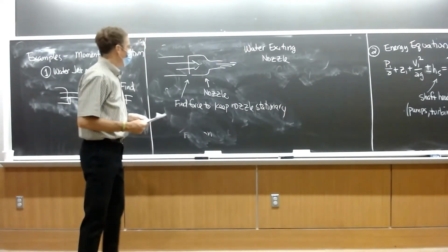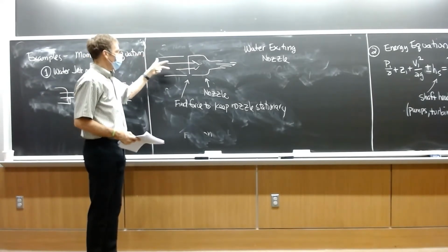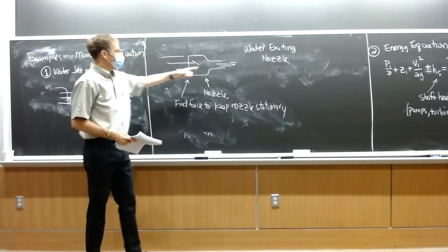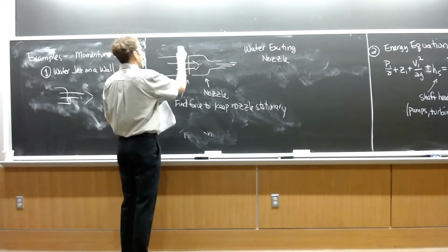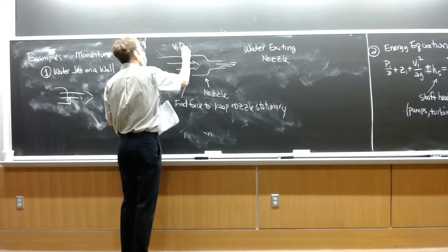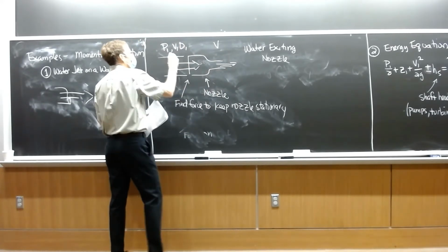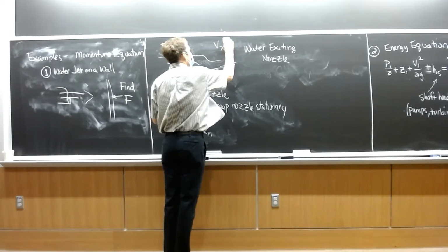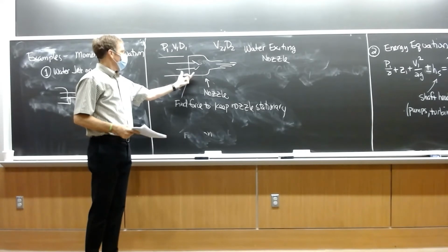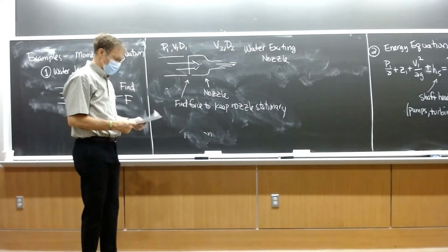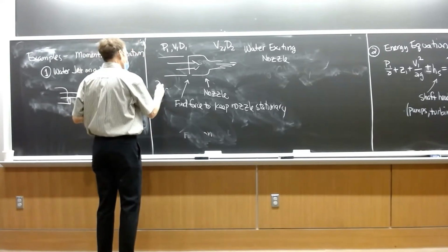So imagine we've got a pipe bolted to a nozzle and water, a particular flow with a constriction, higher velocity. We're given, say, V1 and D1, and the pressure, and V2, and asked to calculate the force necessary on the bolts that keep this thing together. That's solvable with the momentum equation.